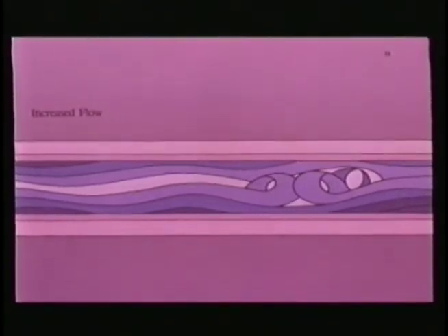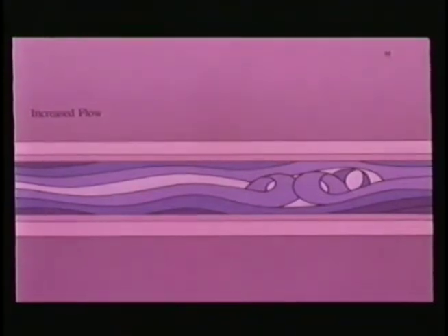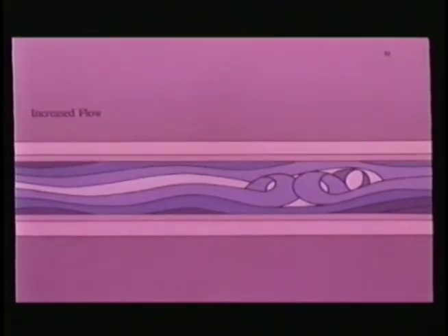32. As the flow rate increases, the fluid particles gain momentum. This magnifies any deviation from straight streamlines and results in an instability of motion. Instead of slipping past one another, as in pure viscous flow, the fluid particles interact with one another due to their momentum. As the flow pattern becomes less orderly, there is a transition from laminar flow to turbulent flow.